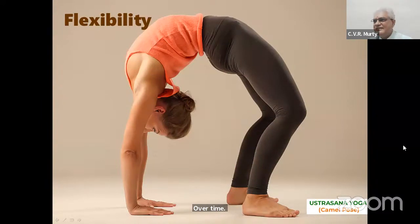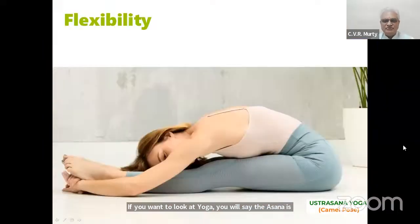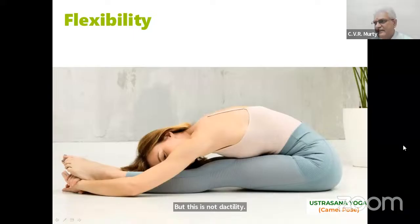What is flexibility? If you want to look at a yoga asana, you will say the Uttarasana is our example of how to bend backwards and how to bend forwards, both of them. But this is not ductility, this is flexibility. In many texts and documents, we have read that ductility is shown like this, which is not true, because all of these people are not going into inelastic behavior. If they go into inelastic behavior, they won't stand up again, right? So they are all within elastic behavior only.